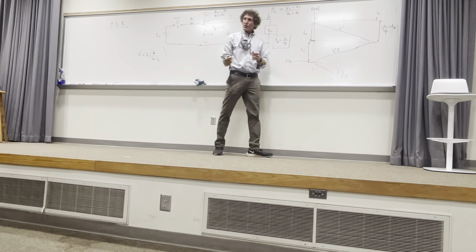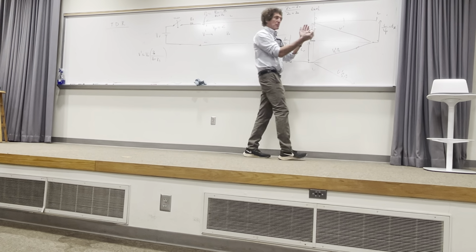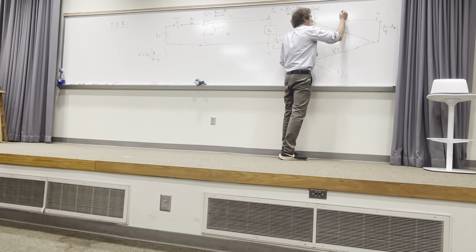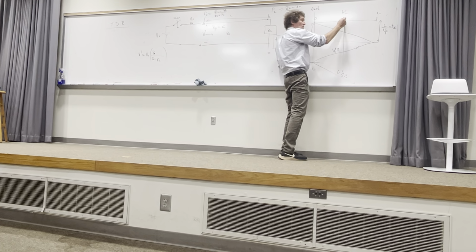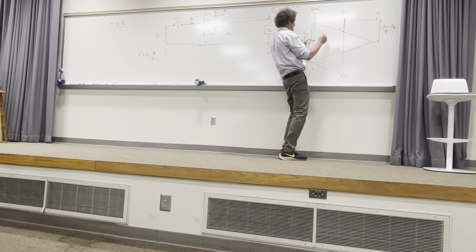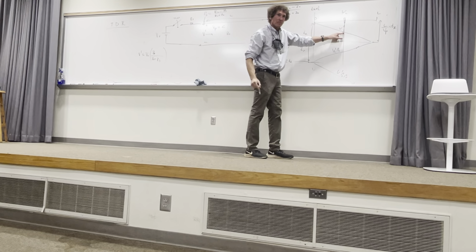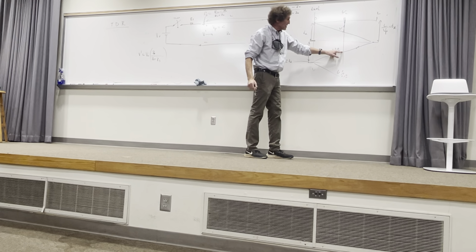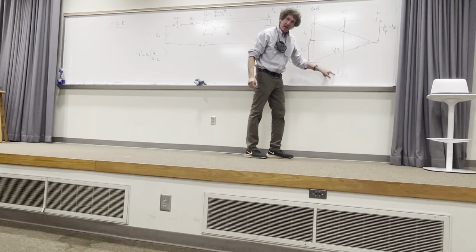And here's the deal. If you wanted the voltage at any point in the transmission line, please just listen to this and then I'm done. Pick the point. Say it's right at the center at L over 2. And you want the voltage in the line, you go straight down and you keep going. Now remember, this axis is time. There's no voltage on the line until I hit T line over 2. Y'all follow me? Then it jumps up to this value, V prime. And it's gonna stay there until I'm down here, which would be T line. Y'all with me? Then you would have to add to it this voltage. Then you keep on going down, hit here, now I add this voltage.